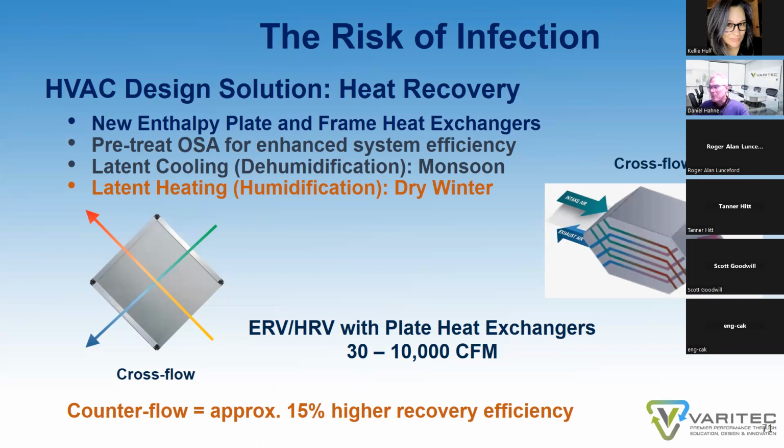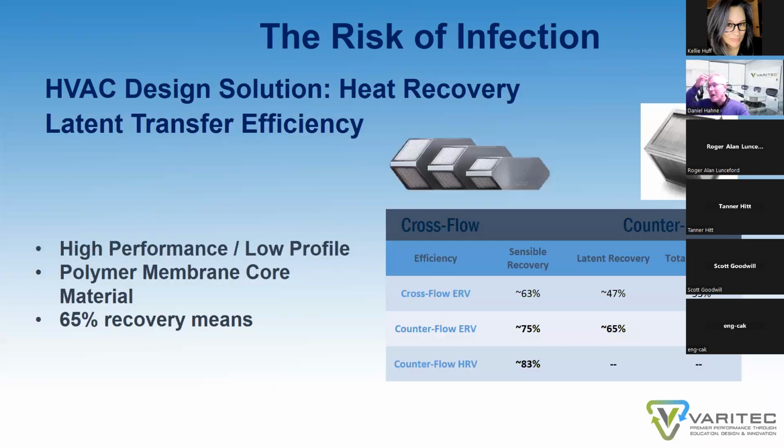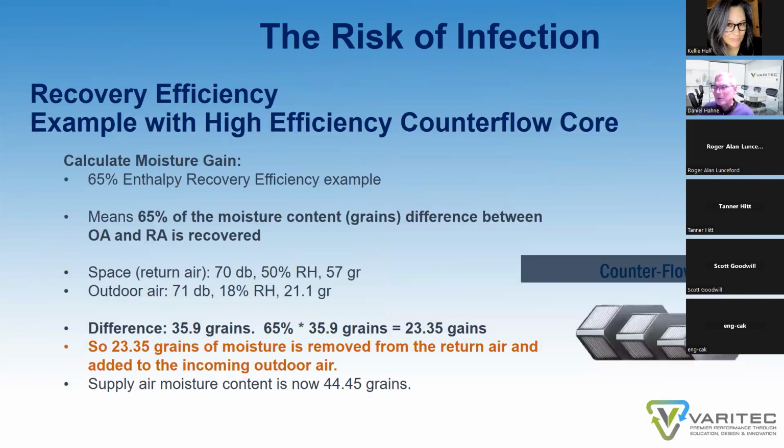they can come in cross flow or counterflow applications. The new heat transfer medium uses a polymer membrane core that is 65% recovery efficient of latent energy, latent moisture. Well, what does that mean in a practical example?